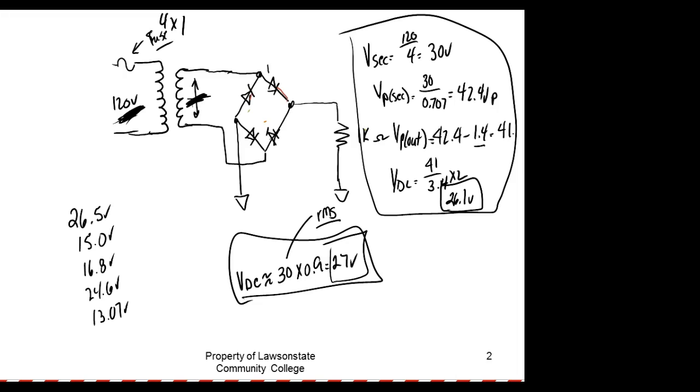And the other one, filtered power supplies, are easy. So if you want to use 0.9, that's okay. It probably won't be on your formula sheet unless I can find a place to put it. But y'all see where the 0.9 came from. It's pretty neat. They just took the RMS value and divided it by the average value of an alternation. And then they divided it by what we do to convert it into VT. 0.707 is pretty neat.